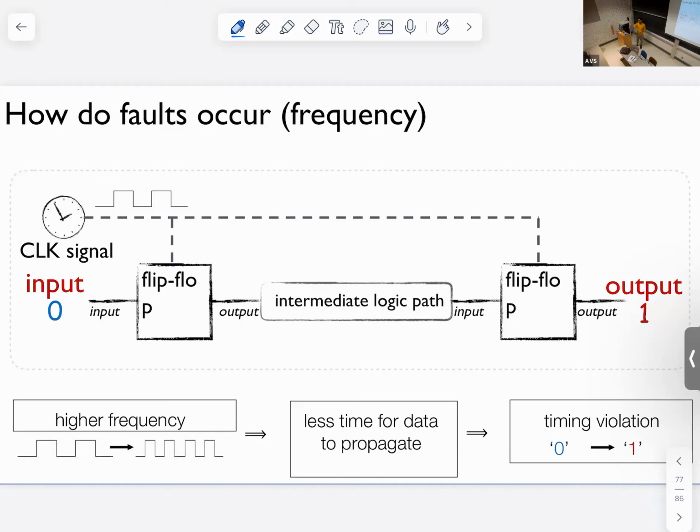So to give you an idea, a flip-flop, as you know, is a unit that works with the clock and stores some values, right? So they are storage units in our circuits. If you have an input and the clock comes, they are usually edge triggered, which means that on the positive or negative edge of the clock, they sample whatever input they have to the output. So the clock comes at this point, this input is stored here. So they have some memory.